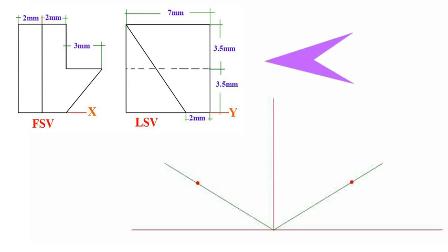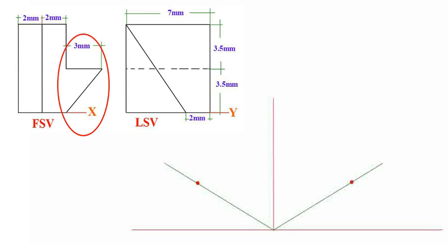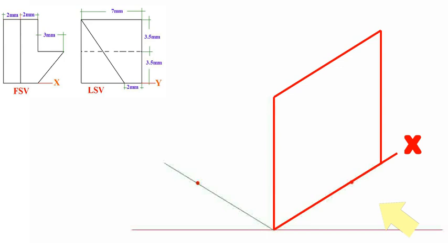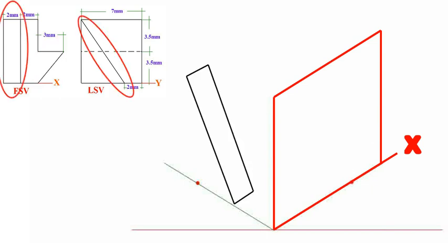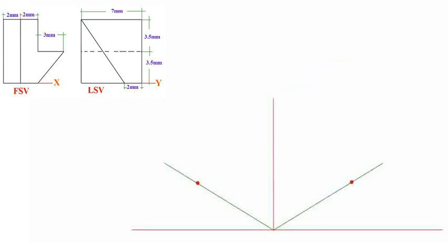In our specific drawing, the object possesses unique characteristics, including a tapered surface and inclined planes on both the right and left sides. To effectively showcase these features, we must select the appropriate side of the axis, specifically the x-axis, as the front. By doing so, we ensure that both the tapered surface and the inclined planes are visible in the isometric view. If we were to choose a different orientation, we might miss the opportunity to observe both features simultaneously, which would detract from the clarity and effectiveness of our representation.